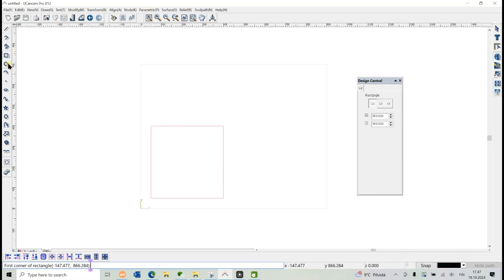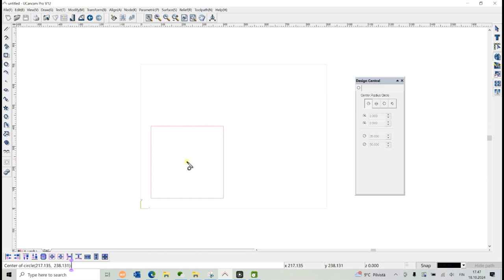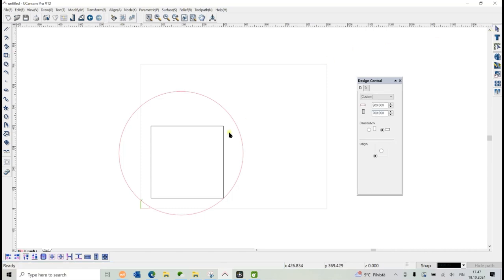Let's make a circle inside. So this is the circle. I could calculate, but I can just make a circle here. And it asks me for the radius at the bottom. So let's say I say 300. And then, oops, totally wrong. So I go here, this is the point, the arrow, the picking tool. So I pick the circle like this.